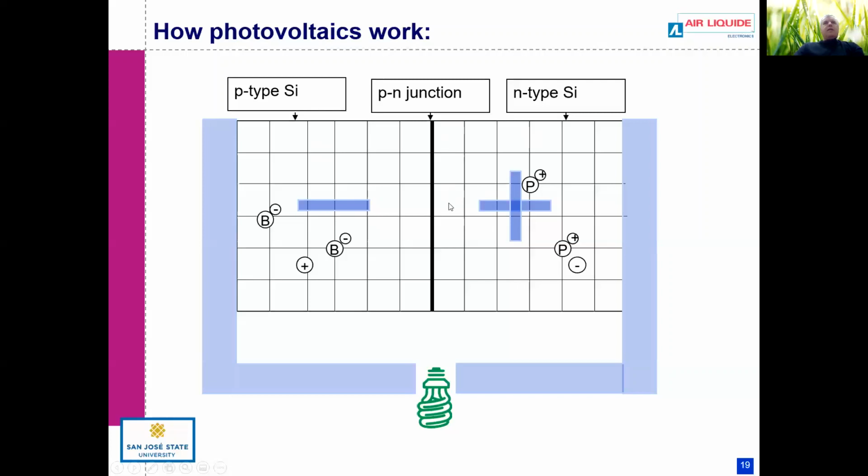And that's sort of normal. It's like a big old dipole moment that happens at the interface between these two materials. And the weird thing is that they conduct electricity, but there's this depleted region here, right? Because this side can only conduct using holes, this side can only conduct using electrons. When they annihilate in this region, it depletes of carriers, so this region here is not that conducting, and there's an electric field across it, right?